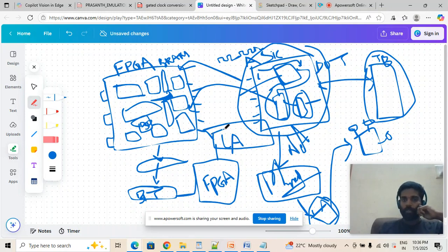Here you can add all your signals, okay, your clock, your reset, and the other inputs you have. For example, you're debugging some DDR level or AXI level. You can add all the write data, read data, and all the write and read channels, and see how they are responding in the real-time hardware, whether my functionalities are working as expected. For example, I connected all my peripherals like Ethernet, USB, PCI. So I try to validate all my peripherals in my hardware.